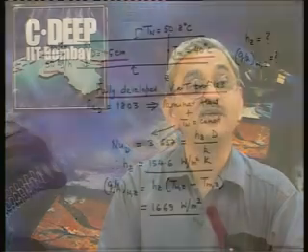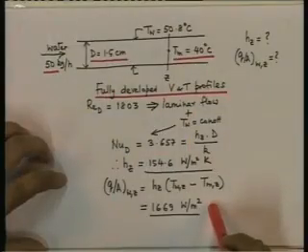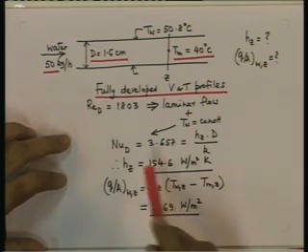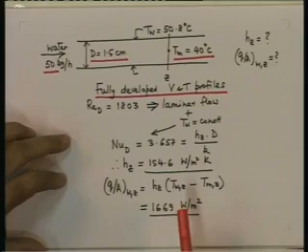And in the second case, we have determined perhaps a lowest possible value for the heat flux, because during the development region, the thermal entry length, the heat transfer coefficient will be higher and hence the heat flux will also be higher. So, remember that the fully developed situation acts as a limiting situation for the entry length problem.